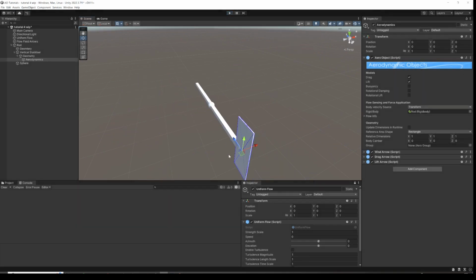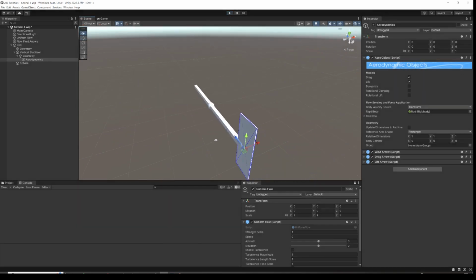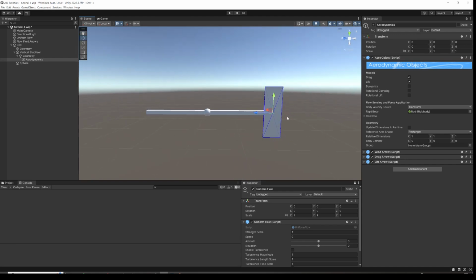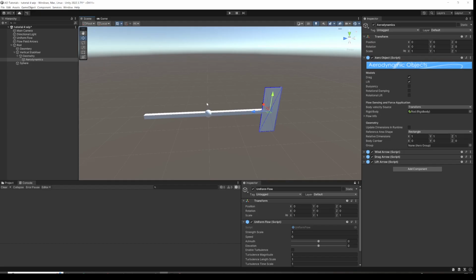So that's a weather vane, and really all a weather vane is, it's just a wing on a stick, and that wing has a force on it, and it moves the stick until the forces go to zero. Okay, that's working just in the azimuth direction, but why not make a weather vane that points in any direction? So if the wind's coming up or down, can we make it so it points into that? So it's kind of universally stable, that it always points into the wind.